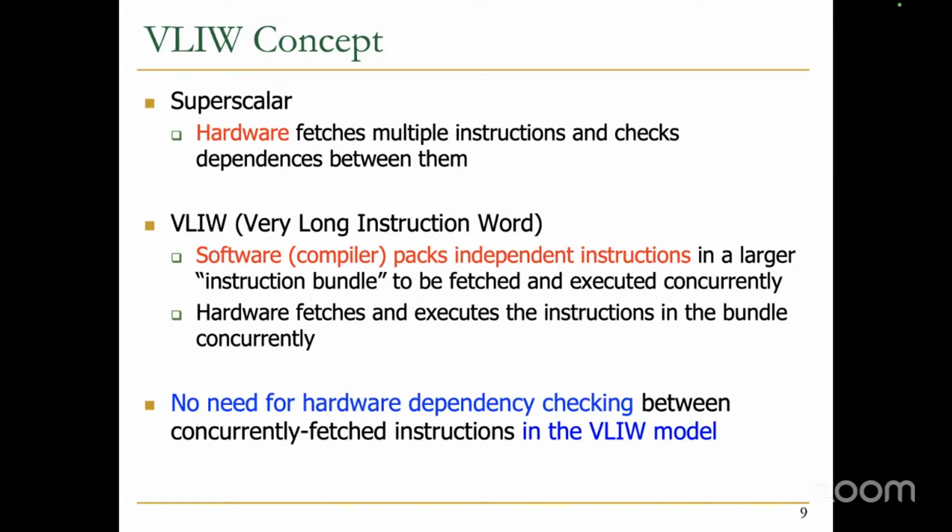So essentially, this is not only done in the pure VLIW model. You don't do it just vertically, but you also do it across the pipeline stages, meaning horizontally in the pipeline, such that hardware doesn't need to have any dependency checking. You eliminate dependence checking hardware. You put that burden to the software. So software exactly knows the microarchitectural structure of the pipeline. It knows there are so many stages. It knows how many cycles each instruction takes. It knows how many instructions the hardware is capable of fetching concurrently, and does all the dependence checking, instruction scheduling in those pipeline slots. That sounds like a beautiful model, if it works, of course, right?